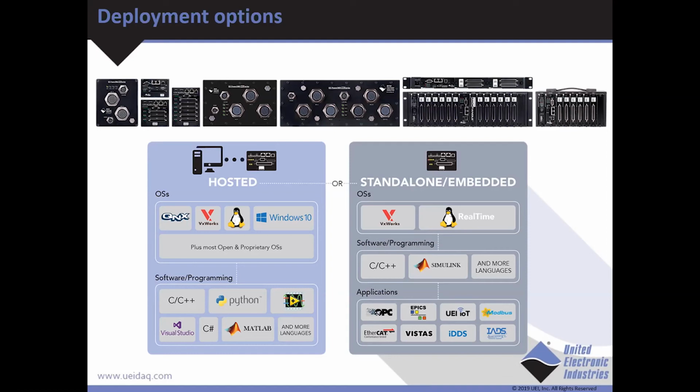On the other side, we have the standalone or embedded mode. This is where the application software actually runs on the unit itself. So you wouldn't need a host PC to run the application. You could just compile the application into an executable, load it onto the hardware, the CPU of the UEI hardware, and just run it there, and you can collect the data on the onboard SD card or SSD device, which is built internally.